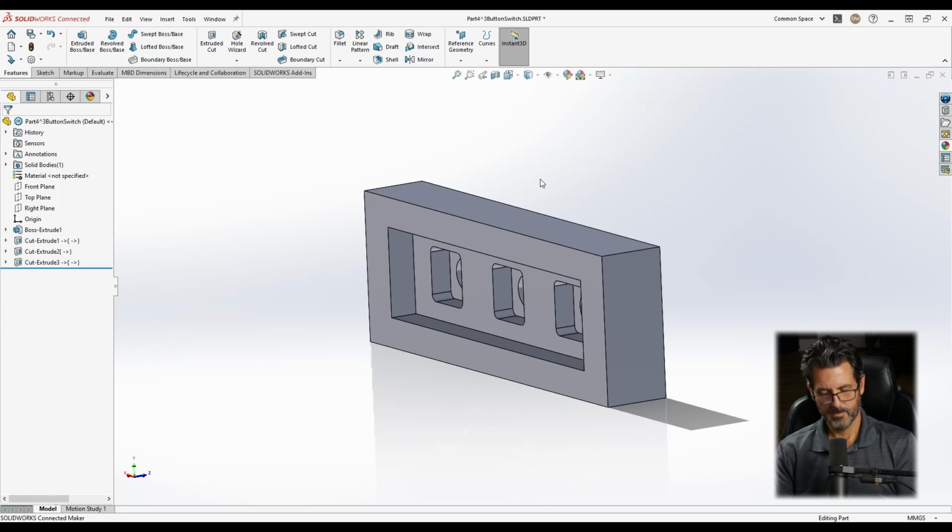So anyway, I have a screw here that I'm going to use. It has a 7.5 head on it. Is the diameter, so we need to keep that in mind. And then the shank is, I basically need a 4 millimeter hole for it to go through. Did I say 7.5? Yep. Okay. Write that down. 7.5 and 4. Okay.